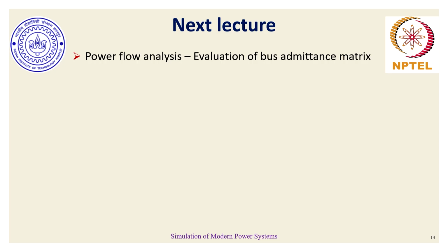discussion. In fact, our next lecture would begin with the power flow analysis module, which is the first module, and we'll start with the evaluation of the bus admittance matrix, which forms the backbone of the power flow analysis module. And in this admittance matrix evaluation, we will see, as the time comes, how we consider transformers when they are at their off-nominal tap position.